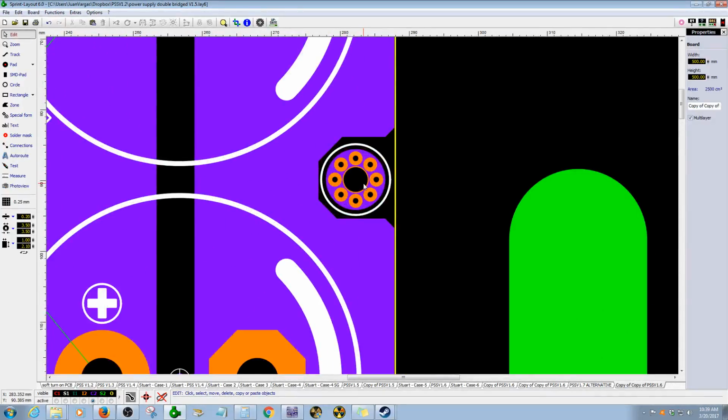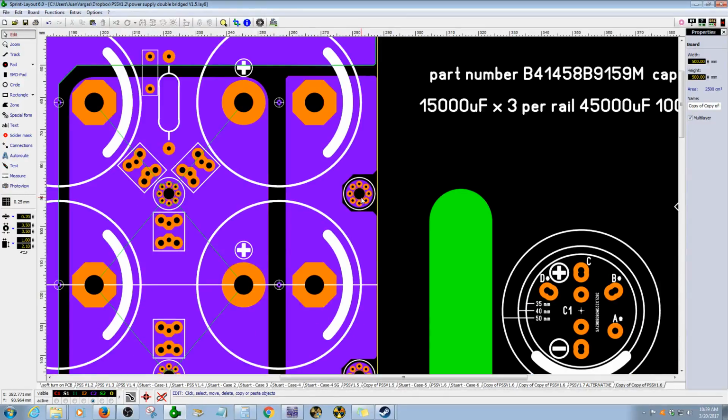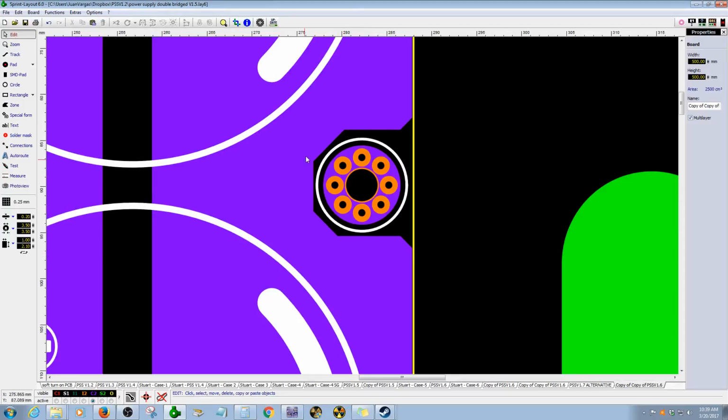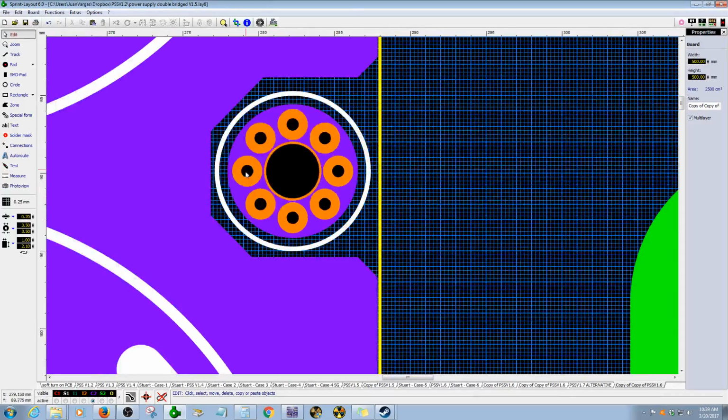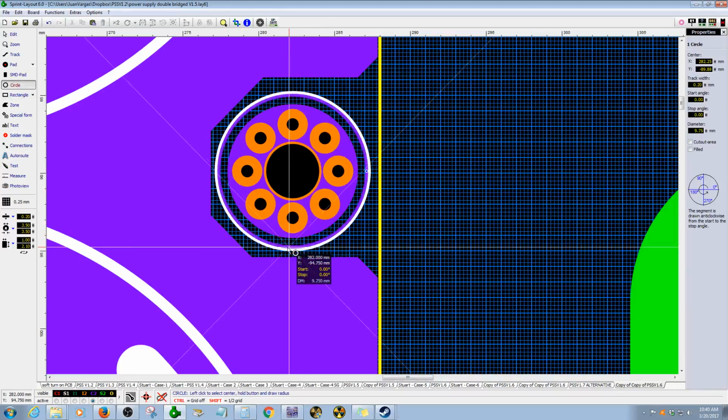The standoff can be made of metal, and for example, if you have a metal standoff touching copper, you're not going to be able to use it to secure the PCB to the chassis. That's why I gotta give some space. The diameter of this screw mounting point is, I think, 8 millimeters. So for example, I'm going to trace the line. Let me see, I got 9. That's okay, I got more. I think it's 10. It's fine.